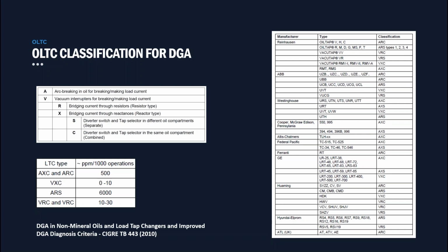If there are no problems identified by the dissolved gas analysis, then it's questionable whether you would do the testing, but certainly it's one of those tests that you can think about doing if the dissolved gas analysis indicates problems.